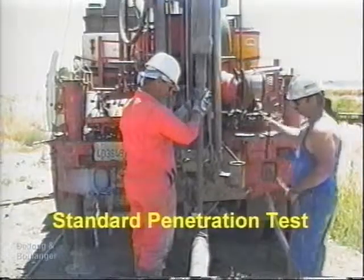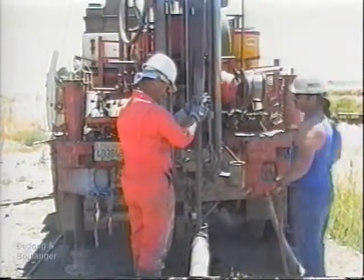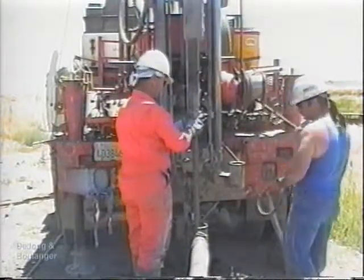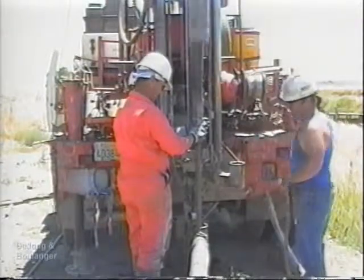A relatively simple and standardized method for estimating the compactness or stiffness of the soil in situ is the Standard Penetration Test, or SPT. This test consists of counting the number of blows of the hammer required to drive the split spoon sampler a specified distance into the ground.